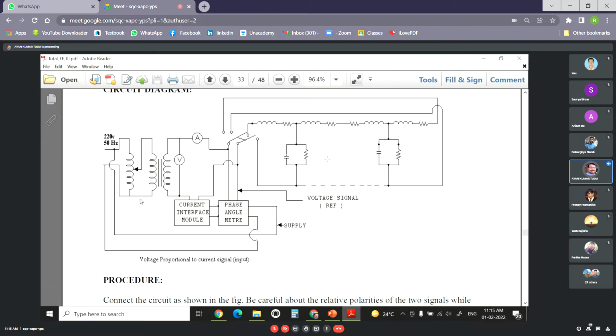So basically we'll be taking the average of the impedance values for the two voltage cases, so that our mean lies around the knee point of the inductor magnetization curve. Okay, so what we'll be doing,